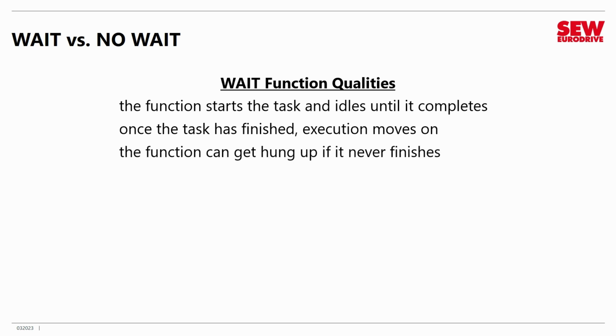However, the disadvantage is the function can get hung up if whatever it's doing never finishes. For example, if you go into referencing mode and you never successfully complete referencing, the program's just going to be stuck waiting for referencing to complete forever. That's not so good. In certain circumstances, this really can mess you up. It's not a great thing always. And that's why the no wait function does exist.